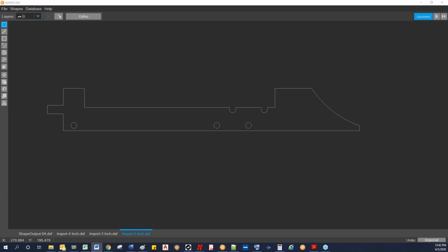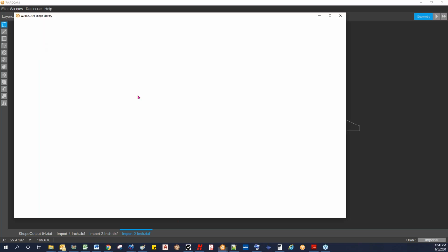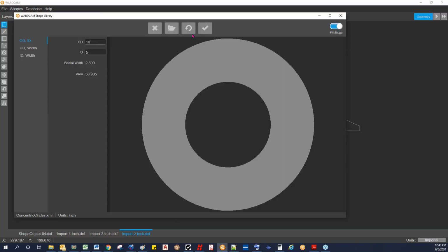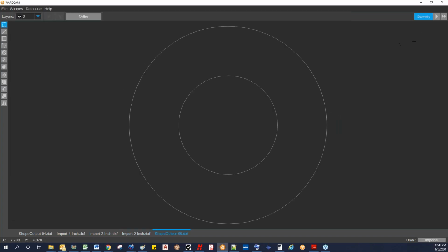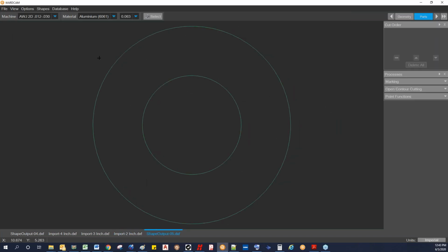And then finally I'll show you a part doing some circular low pressure piercing. I'm just going to go for a part from the shape library here. If we're going to cut this part out of glass, we hit our next button, and I'll switch to the 1440 machine, 1440 nozzle combination, switch to glass, switch to whatever thickness.